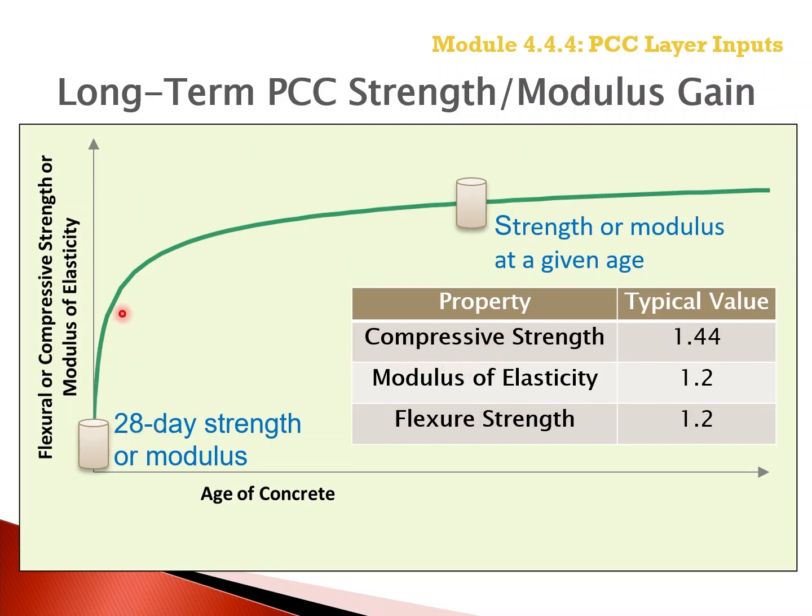So not only the time dependent 7, 14, 28-day, and 90-day strength, but the 20-year to 28-day strength and elastic modulus value ratios are used in predicting the growth of those strength and engineering response values throughout the design period.